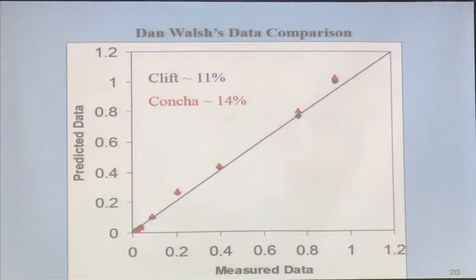Okay. So then I got 11% and 14%, not much difference, but still I would prefer the iteration method over this. And unfortunately, the size range he has dealt with is a very fine size range, and we have seen that even with synthetic data in a fine size range, not much deviation is there. If it is coarser particles, I am very sure these differences will go up. So personally I recommend that if you think your settling velocity information is very, very important for your design purposes